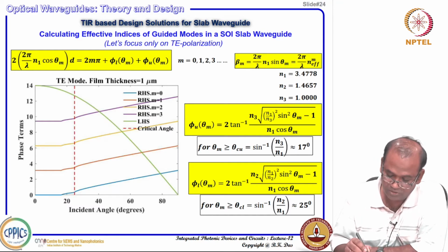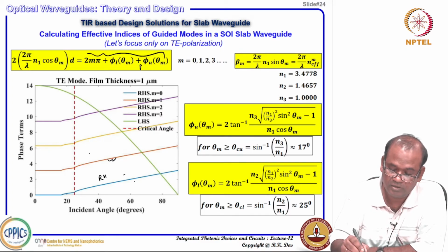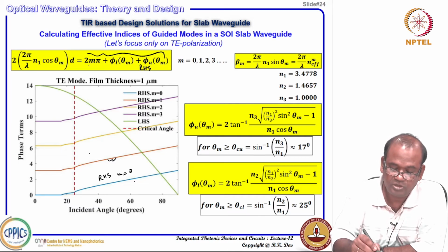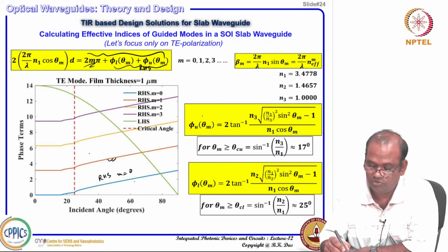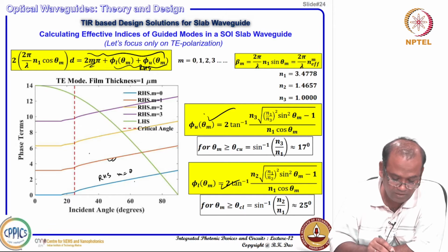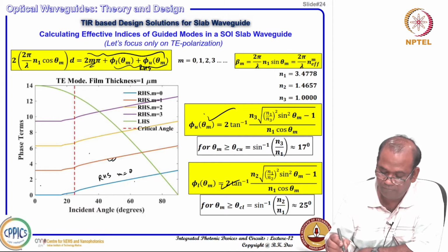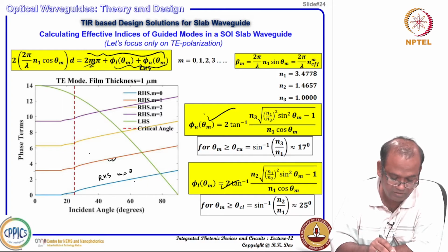Yeah. So, this is solved for the right hand side, for m equal to 0. This curve, that means m equal to 0; I am adding this 2 pi, then I get this curve. Just use this curve and this curve, and then you plot m equal to 1. I think what happens in this curve, it is supposed to be 2 pi, means 4 pi, but here you have added just 3 point something pi.